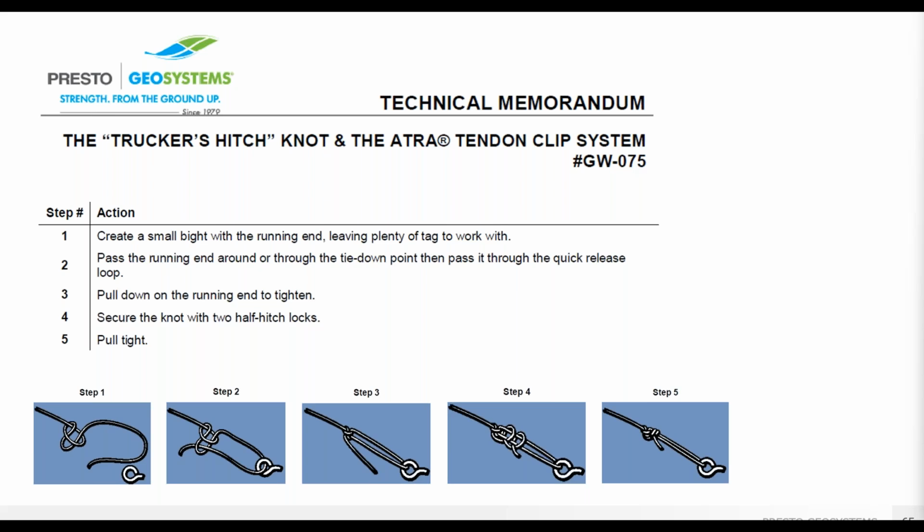One recommended knot is the trucker's hitch knot, a self-binding knot common for tying loads to secure them to a fixed point. It can be tied anywhere in the standing part of a line and can create high tension lines that can be used to safely secure heavy loads. Here's what that knot looks like.